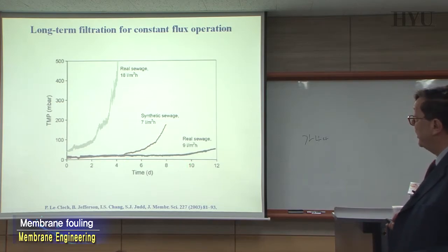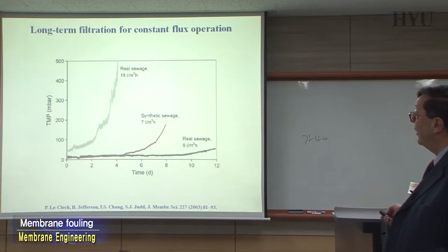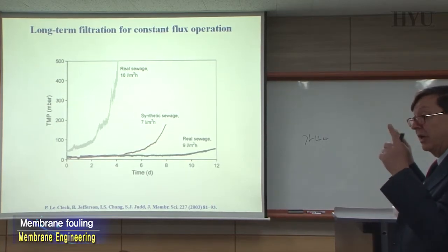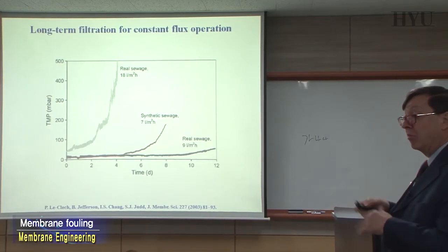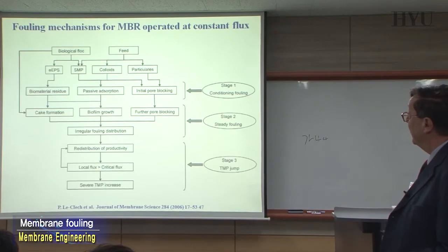In some cases you can observe that you start to deviate, the pressure drop is increasing, but you also have a situation of this kind, where suddenly, in a bad case, when you are working with high transmembrane flux, the transmembrane pressure goes up and you have to stop the plant. You can block everything. The driving force becomes not sufficient for solving any problem.